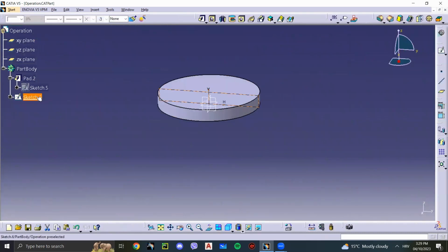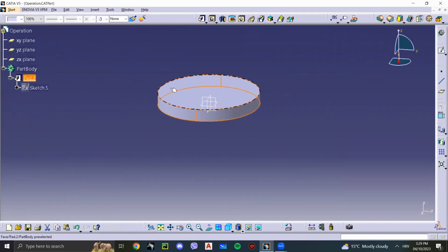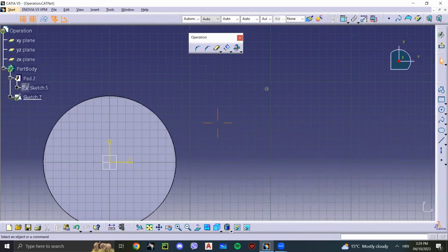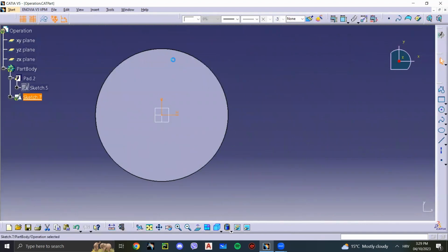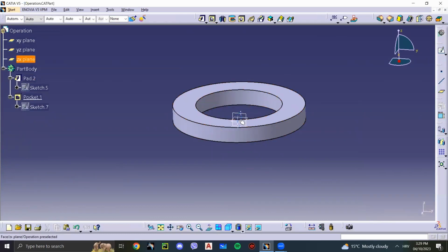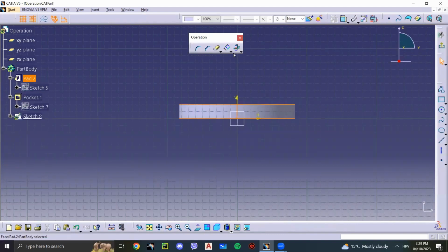Now, for the next one, we just delete the sketch, yes. Let's go sketch here and make a little hole. Let's just make this, deselect, use the pocket command. We want the depth to be 20 millimeters. And now again, select the side view. So when you project this with 3D elements with a spherical thing, it will not give you the edges.